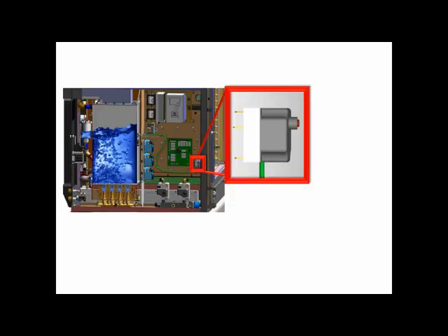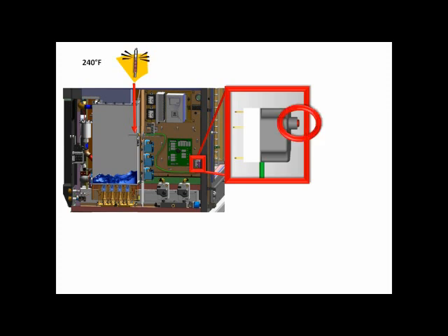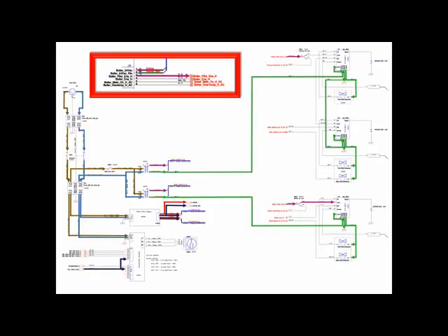The water continues to diminish as it boils away and a dry fire condition results. The boiler limit thermostat registers a temperature exceeding 240 degrees, and the high limit's manual reset button pops out. When the limit trips, the output to the module is stopped and is sent out the normally open contact of the limit to the relay board.